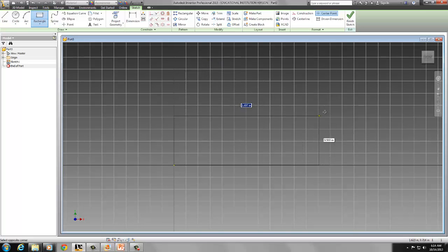So you can see up there we've got the highlighted area. It's 1.521 inches. What I can do there is just put in 1.5. Okay? If I hit enter, it's going to close things out, so I want to use tab, and that'll tab me over to the vertical direction, and you can see right now it's 0.62 inches.